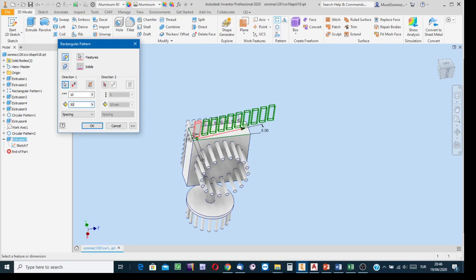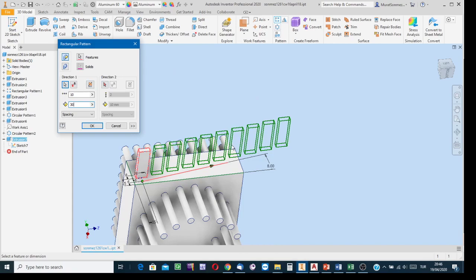You see, I am trying to find the number just in this demo because I didn't make any calculation of how many members can be created over the surface. So I said 10. But I see that 10 elements cannot be created at 30 units apart over the surface. I see 3 of them will be in the atmosphere. So say not 10 but say 5 totally. Or 6, try 6. I think 6 is okay. And then click on the OK button.